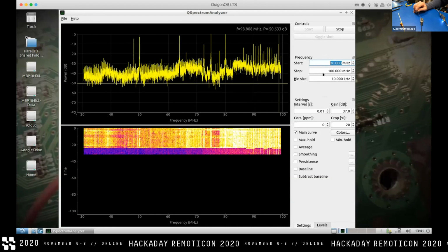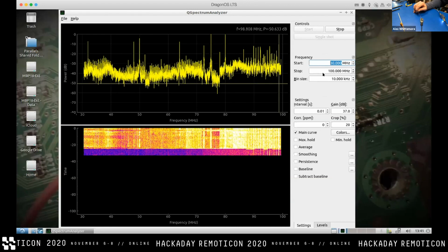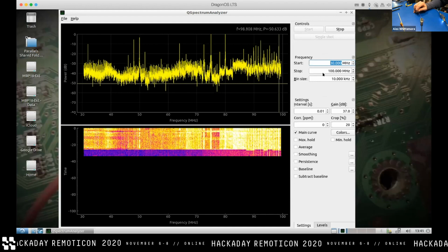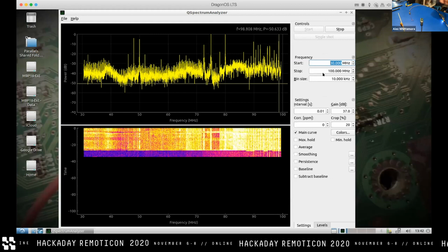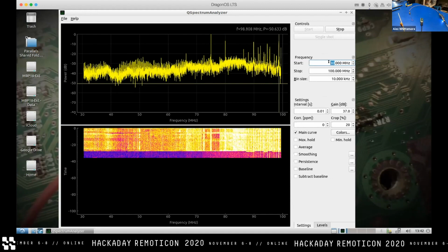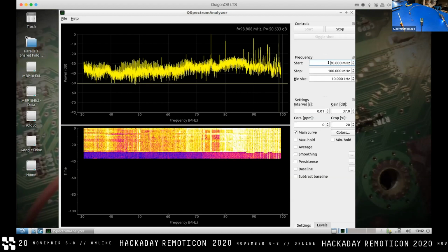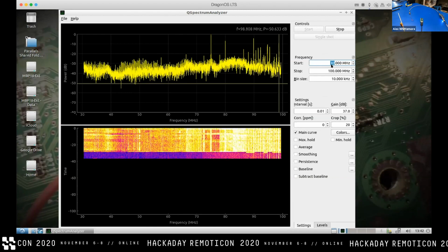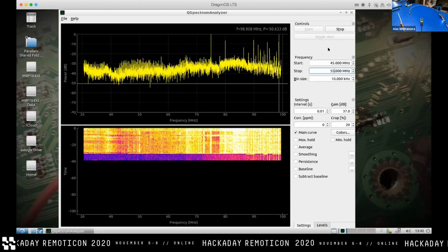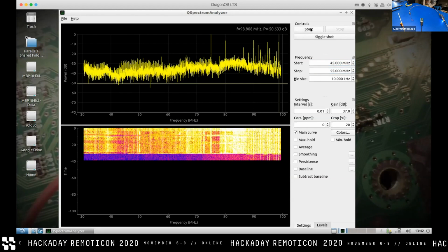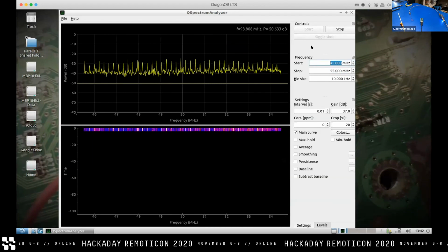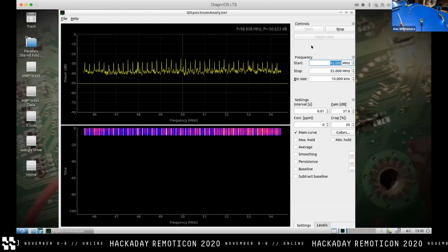But anyway, what we do now is, okay, we see those peaks. We see 48 and 50 megahertz as definitely peaks. So let's narrow our gaze a little bit and search just between 45 and 55 megahertz. My keyboard is again not working. 45 and 55 megahertz. That's still more than the real-time bandwidth of our SDR, so it's not going to happen instantly. But, oh boy, that certainly happens a whole lot faster.